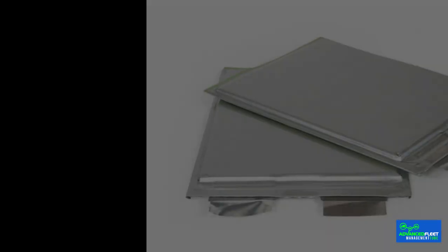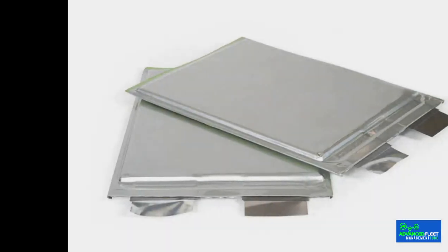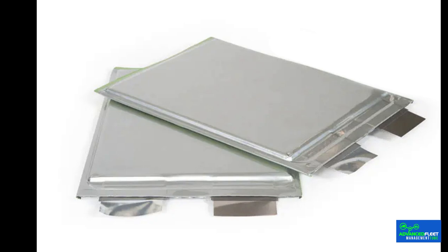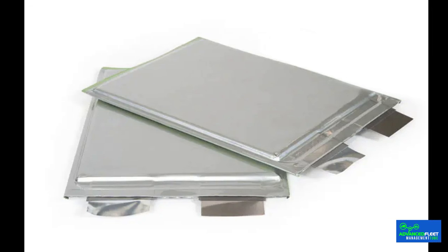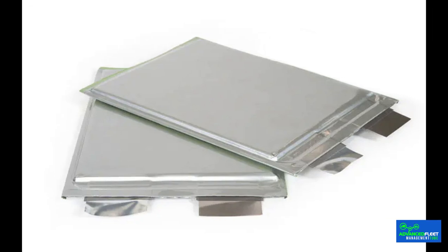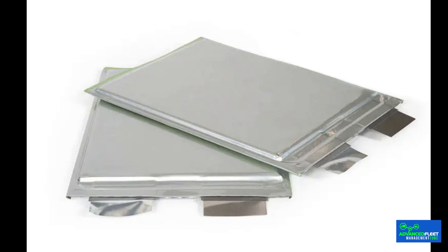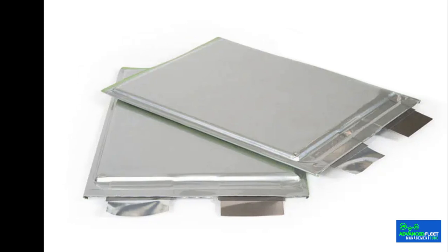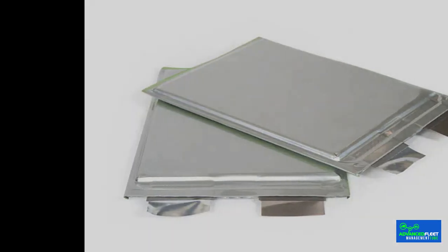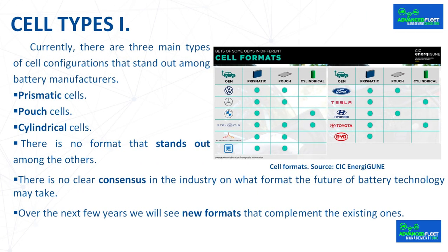Pouch cells. They are characterized by their light weight, thanks mainly to the use of aluminum as a material for the coating, although they also stand out for their small size and flexible cells that can easily adapt to almost any space thanks to a packaging efficiency of between 90% and 95%. They also have a higher energy density. This format is very promising for the future since solid-state batteries can work with this type of cells.